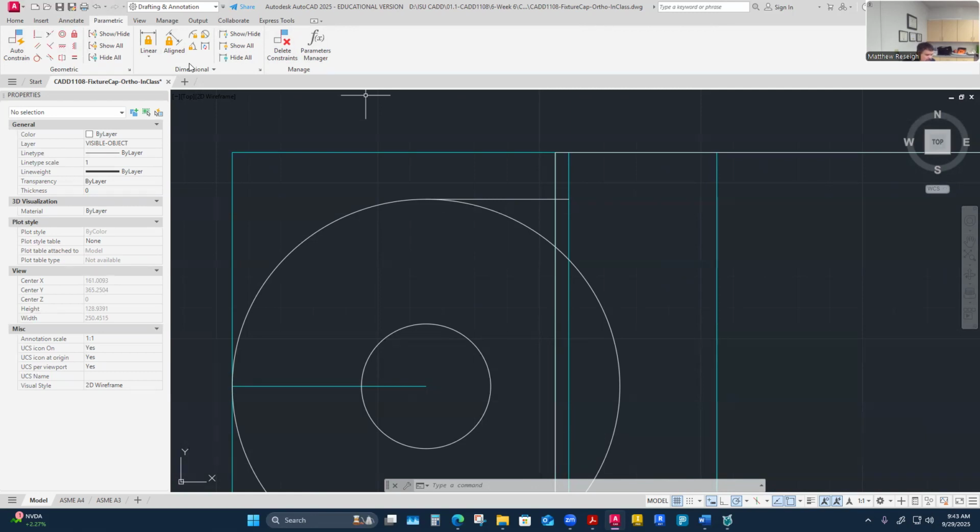I can force them to remain and give them dimensions that can be changed, but I can actually draw something by actual dimension that's locked in unless I go into a kind of spreadsheet that it'll build for me, and then it has a place where I can manipulate the lengths of stuff. But I can also geometrically constrain things. And when we get to this, these are really related to 3D modeling, which is why I love this so much. When we get to drawing in Inventor, we're going to be drawing before we ever draw in Inventor, we're going to draw in CAD using kind of Inventor-esque constraints to our geometry and our lengths.